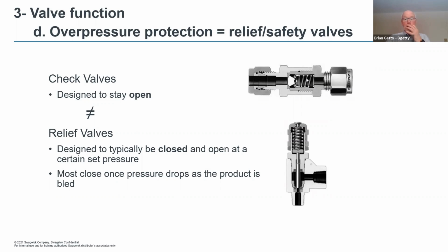All right. Whereas a relief valve is designed to be in a normal position, closed. Should there be a problem with the system, an overpressure of the system, your pressure will be coming in here, and it will push on your poppet or your stem. It'll push on your stem, which of course is held in place with a spring. It will allow a flow, it will dump pressure, and then because of the force of the spring, it'll automatically close it. But again, a pressure relief valve is designed to be normally closed.